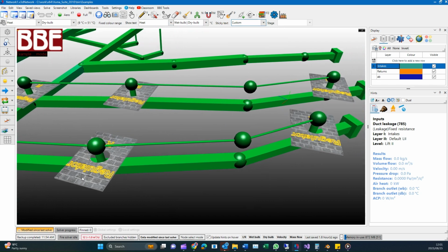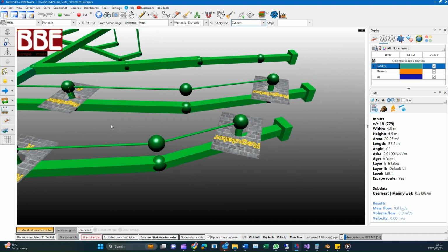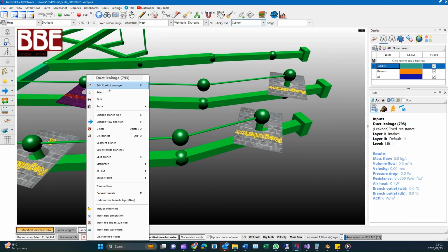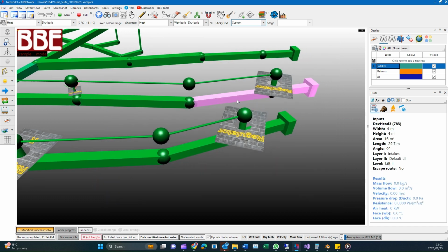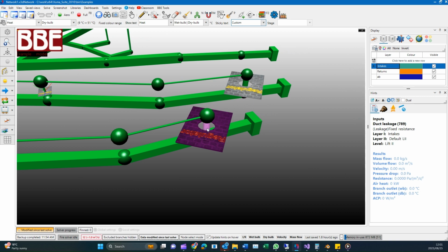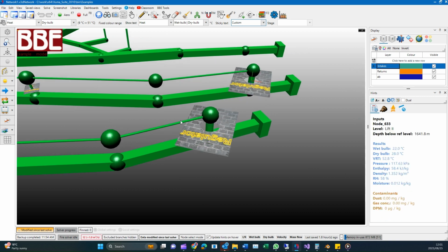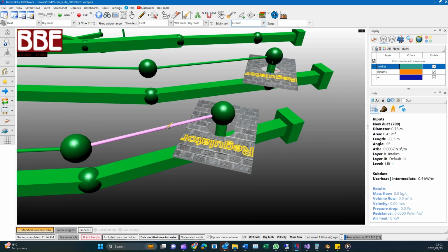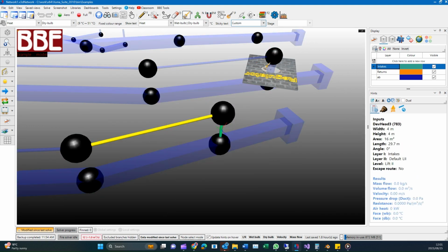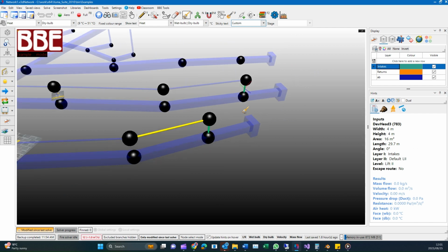Depending on your settings, leakage branches might be added automatically. You may need to alter their respective resistance values for a higher or lower amount of leakage. Make sure that you do not overconstrain the column by having only a leakage branch at the end of the column. Rather use the Format Painter to overwrite the last connecting branch to the same properties as the duct.